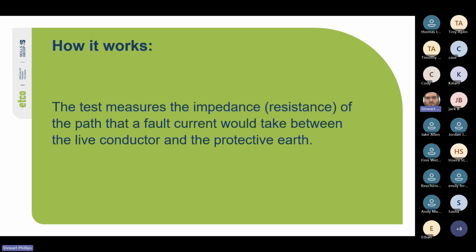Yeah, you may not necessarily know the full EFLI circuit like I described, but you need to know that there's a transformer somewhere in the circuit at the supply side that produces reactance, and so we need to look at it as such.